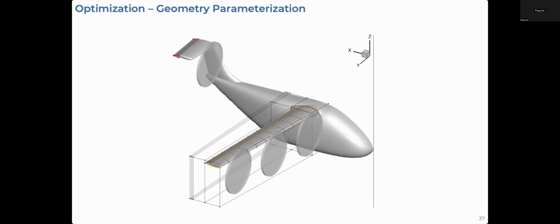This is a frontal view of the deflection of the wing for cruise and maneuver off of the jig shape, which is the baseline. So you can see directly here how our two-way coupling is allowing us to model the wing once it's actually deflected, not just the baseline jig design. The wing distributions for both cruise and maneuver flight conditions maintain aerodynamically optimal lift distribution.